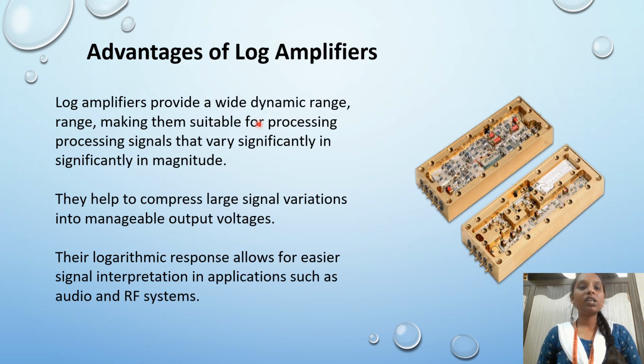Next, advantages of log amplifiers. Log amplifiers provide a wide dynamic range, making them suitable for processing signals that vary significantly in magnitude. They help compress large signal variations into manageable output voltages. Their logarithmic response allows easier signal interpretation in applications such as radio or RF systems. These are the advantages of log amplifiers.